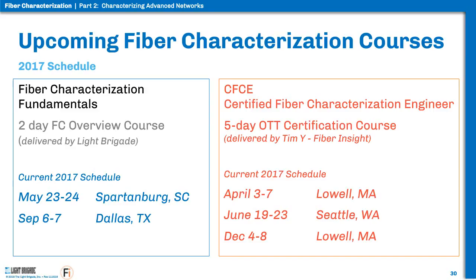I think EXFO actually has a device supposedly that will provide sectional assessments of PMD. I've never used those devices, but I understand that they do have those. So I wouldn't really be able to speak intelligently on that topic to that level. You would need to probably get in touch with them on that. But the methods we talked about today will do span PMD values, and it'll give you numbers for that entire span, but it will not break out those sections section to section. And I'm not sure if there are any other manufacturers other than EXFO that actually offer this sectional value measurement.